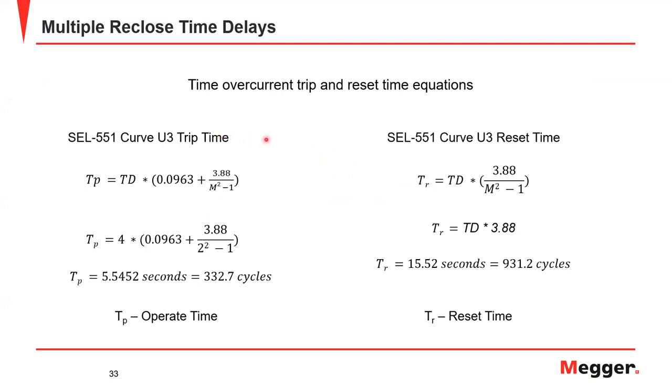So these are the equations for calculating trip time and reset time in the relay that we'll be testing today. And these are very applicable. It's the same curves that will be used in a coordination study to determine where you are. So you have predicted trip time, which involves your time dial, and I believe David talked about that earlier, but mechanical